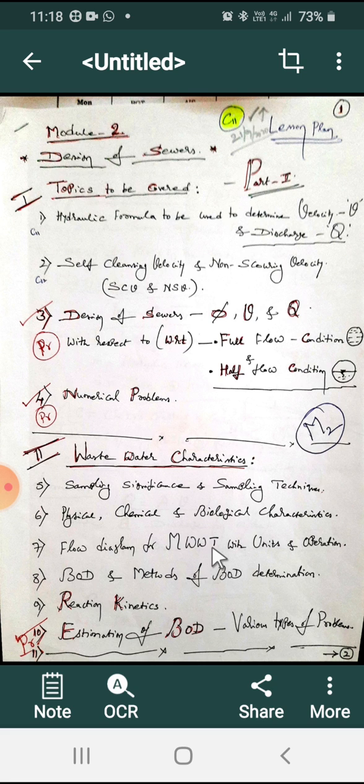Now in the treatment plant, similar to a water treatment plant, this is a municipal wastewater treatment plant. What are the units that will come here? In a water supply treatment plant, what are the units? First is intake works, next aeration, afterwards plain sedimentation, then sedimentation with coagulation, after coagulation filtration, then the filtered water goes for disinfection, then storage, afterwards you distribute to the public.